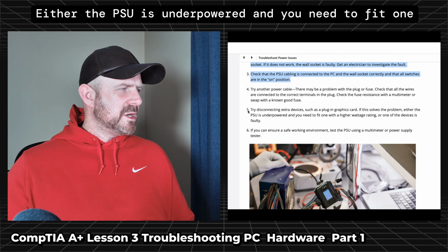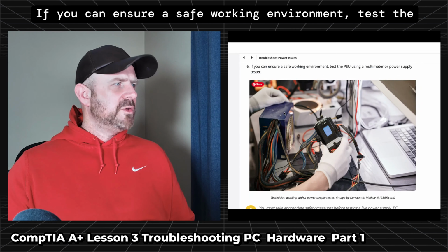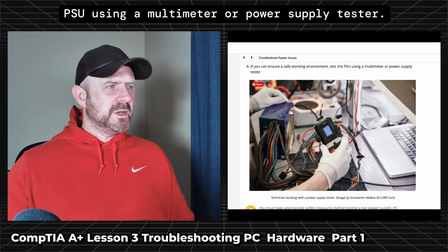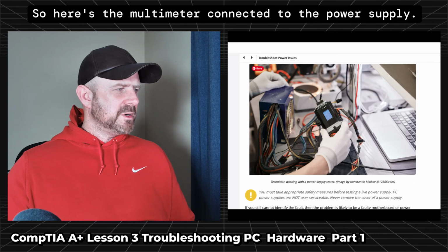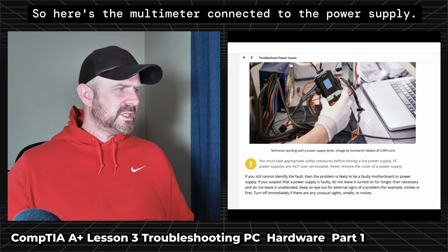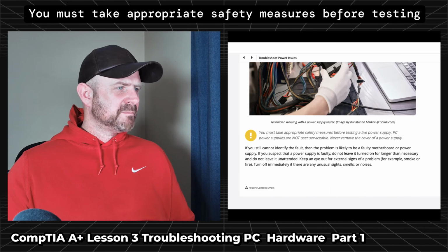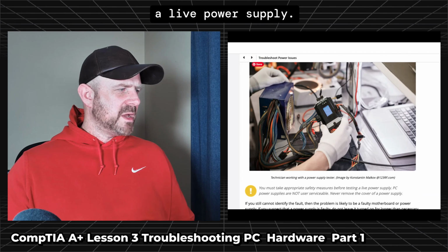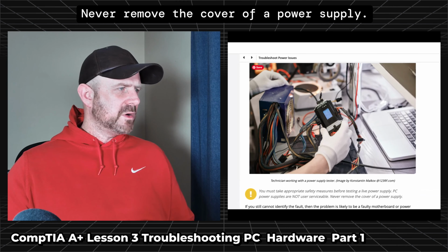Either the PSU is underpowered and you need to fit one with a higher wattage rating, or the device is faulty. If you can ensure a safe working environment, test the PSU using a multimeter or power supply tester. So here's the multimeter connected to the power supply. Test the power of the power supply. You must take appropriate safety measures before testing a live power supply. PC power supplies are not user serviceable. Never remove the cover of a power supply.